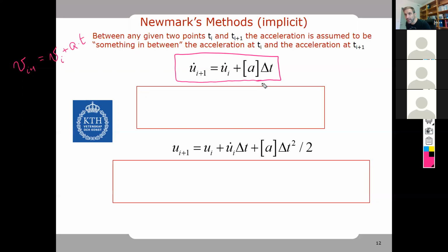So the Newmark method, or family of methods, this implicit method that we are going to explain now, assumes exactly that. It assumes that the movement is uniformly accelerated, and uses these formulas coming from a uniformly accelerated movement to compute newer and newer values of the displacement all the time.